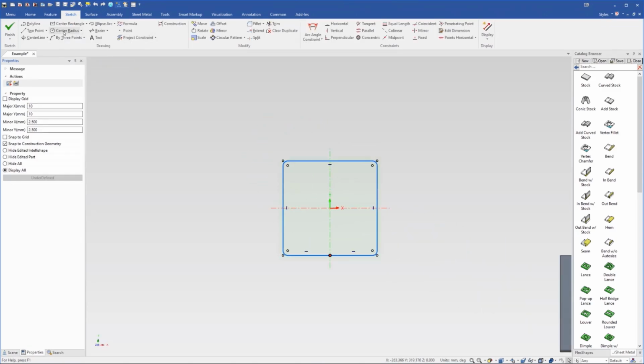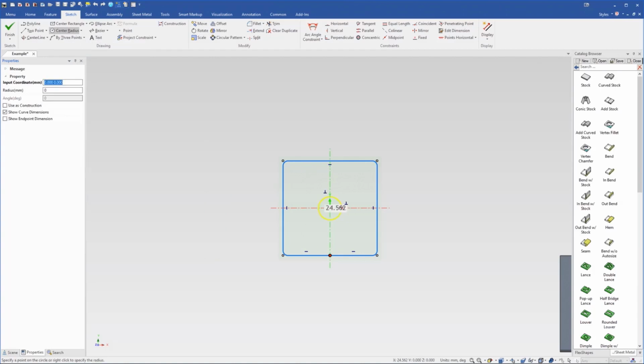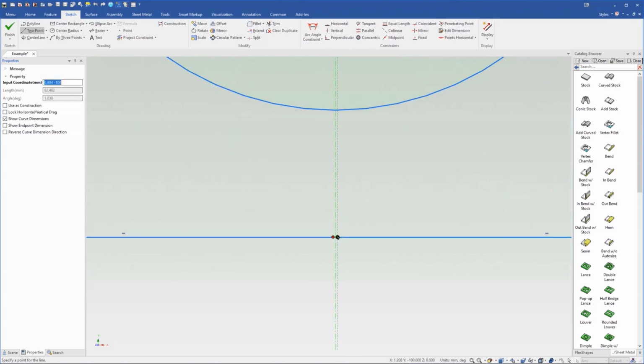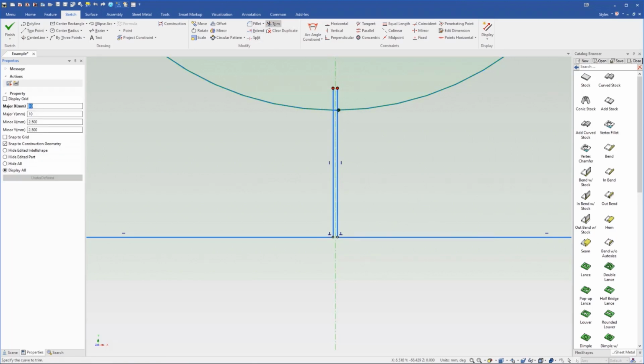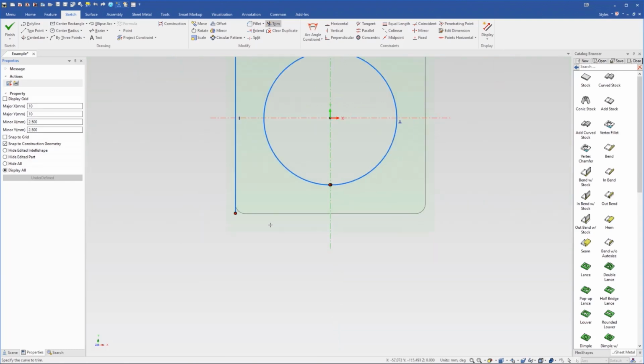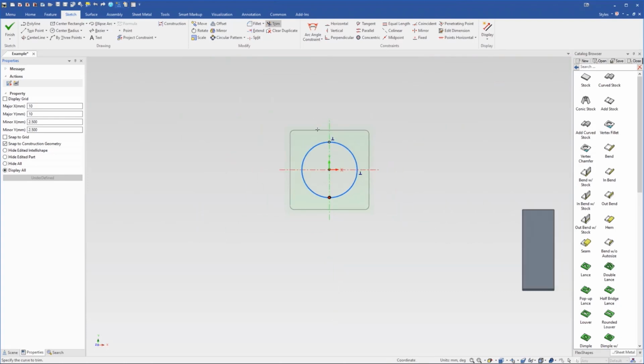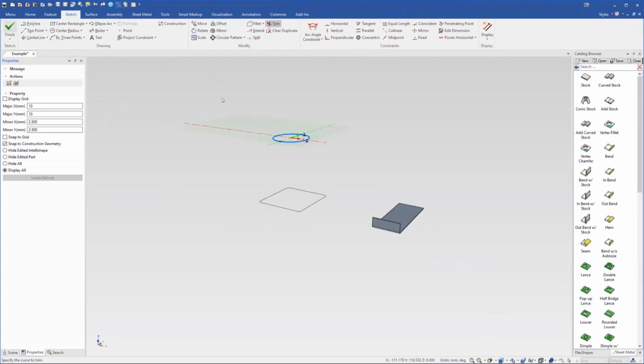Now what I'll do is draw a center radius circle. So I'll draw this here, and I'll choose what size I want it to be. In this case, I'm going to choose for it to have a 70mm radius, so I'll just press the tab key and then type 70 and hit enter. Next, I can go ahead and cut the same sort of cut I made earlier. So I'll do that by zooming in here and just drawing straight up lines from the other two lines, our 2 points we've got on our earlier shape. With that done, I can use the trim tool again, trim away everything we don't need, which is now all the lines in the model except our circle. Like so. Now I'll click OK to finish.